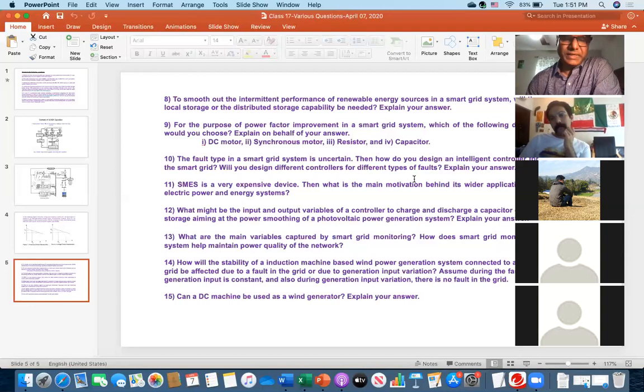On the other hand, if it is only 1-phase, as I said, the most common case, a tree has fallen and is attaching to only 1 cable, and the other end of the tree is still on the ground. In that case, the current magnitude is not that high, and voltage does not go that low. So in that case, a different controller will work fine.